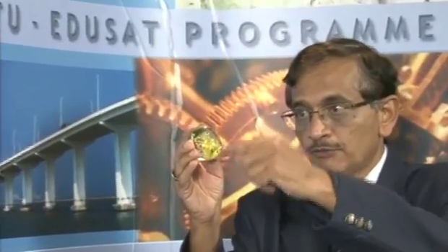Indirectly what I am trying to say is, suppose this is a curved surface. You can see it is a curved surface. I will project this point to this point in the form of a plate, exactly the plate I was showing you, and I will work out the horizontal force. I repeat, I am not bothered what the shape of this is.